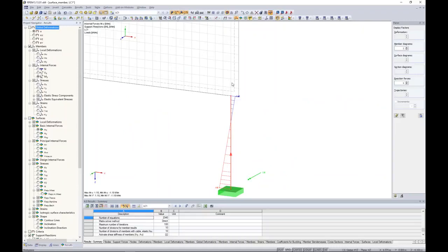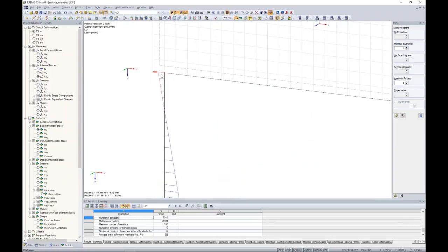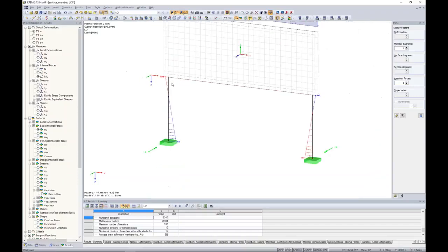And the reason for that is that the shear panel has 3 degrees of freedom, like translational deformations, but the column also has a rotational degree of freedom. And this is an incompatible FE mesh in this node. And we have to think how to connect the column with a rigid connection to the shear panel. And I will show you one solution.